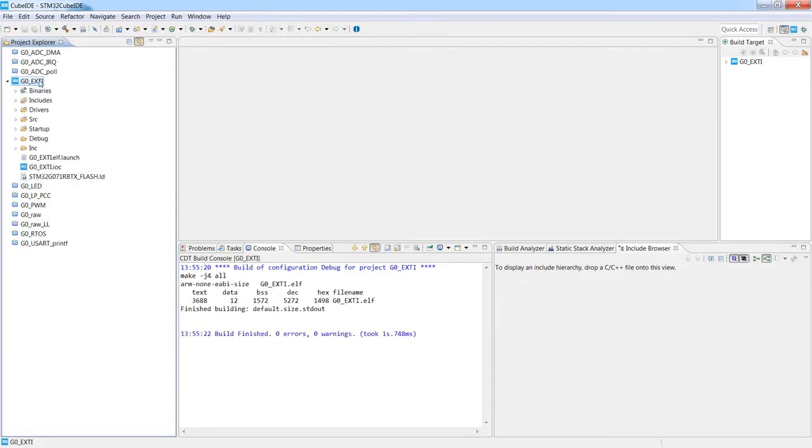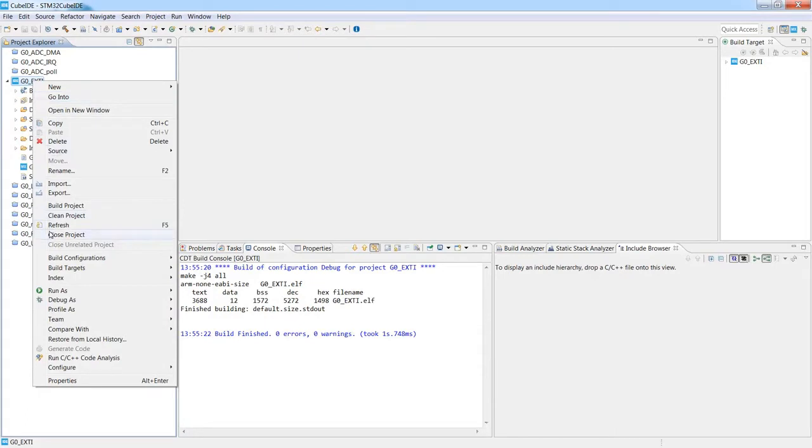Important point is that an active open project can be exported later on. All closed projects are not handled within export operation, which we'll discuss a bit later on. To close the project, we need to click the right button on mouse and select Close Project.